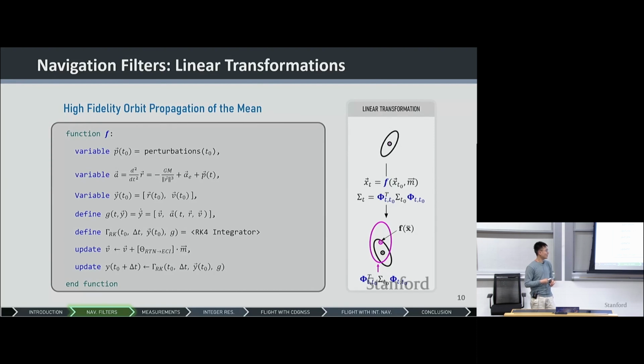And before we actually propagate forward in time, one concept that's very important in a filter is the notion of time. So where you are right now in time, do you actually have maneuvers that were queued in your software? Did your propulsion queue certain maneuvers for you to do some updates? If so, please handle those maneuvers that are being executed right now. So that's T0 right here, before you actually do your propagation. You're accounting for them in an impulse sense. Then once you've accounted for any maneuvers and actuations, you can proceed to do your orbit propagation.